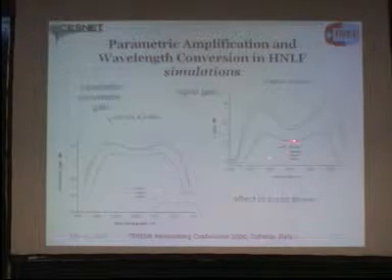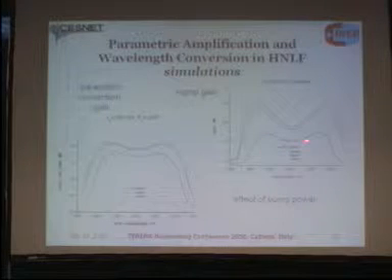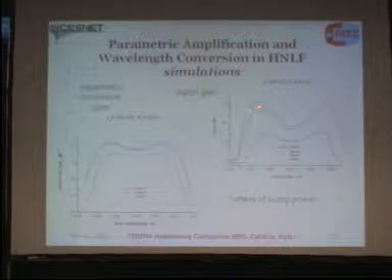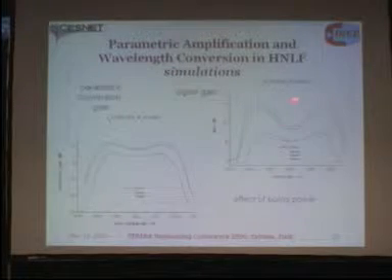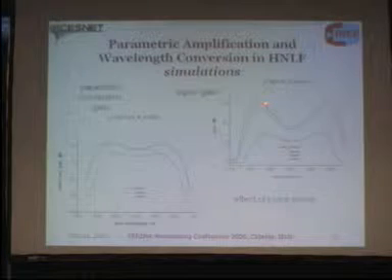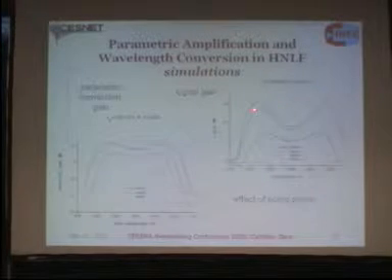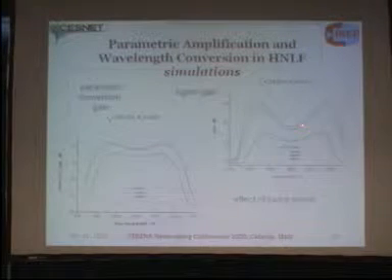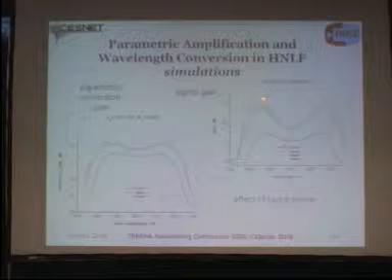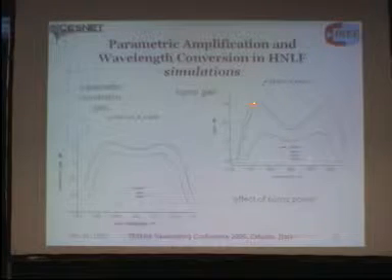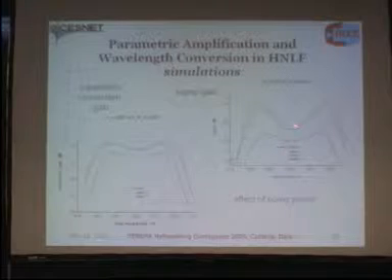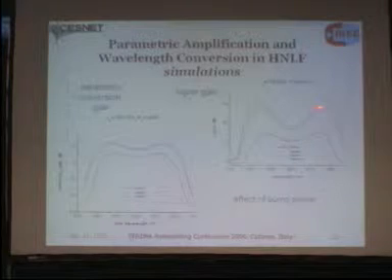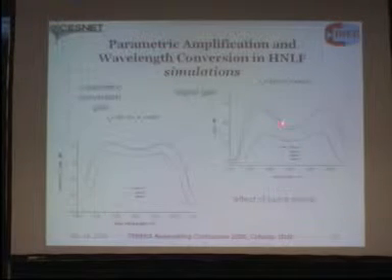You can see the spectrum for different values of the pump power. So the gain increases. If you compare this spectral characteristic of gain with an erbium doped fiber amplifier, it is easy to see that the gain is not flat. There is a big difference between the highest gain somewhere here and the lowest gain, which is close to the pump wavelength. So at the pump wavelength you have the lowest gain, and the gain is not flat.